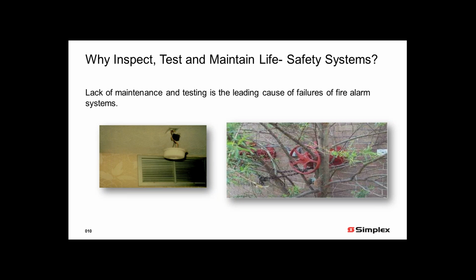So lack of maintenance and testing is the leading cause of failures of our systems. And this is just a couple of pictures that I found over my travels. Like Peter, I travel a lot as well and spend a lot of time in hotels. The picture on the left shows the smoke detector hanging down, and you talk to the maintenance people, and they tell you, yes, we had the ceiling worked on, we had it painted, and that detector's been down, and we've never put it back up, or for some reason.